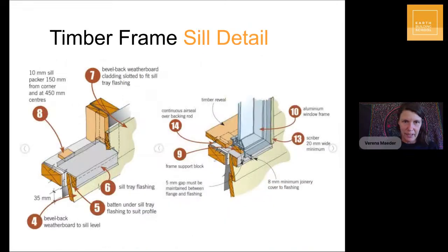And here are some sill details. So again, there are different situations with timber construction for the sills, but one of these is just to put in this sill flashing underneath your timber window that then allows this junction between the window and your cladding to be weatherproofed.